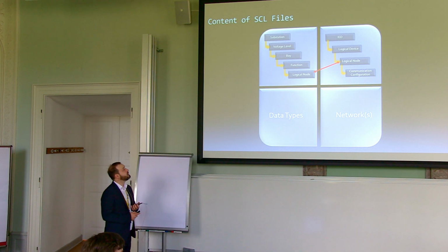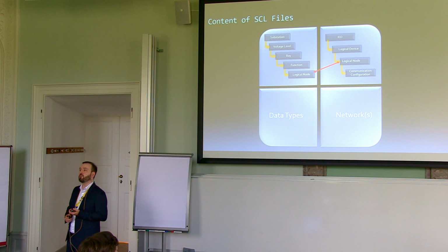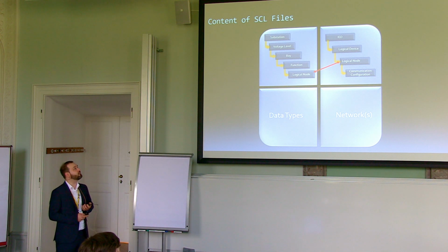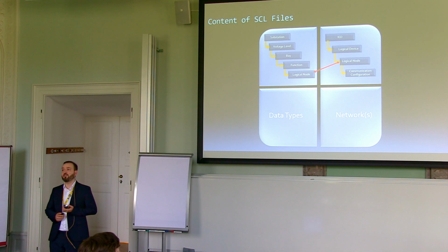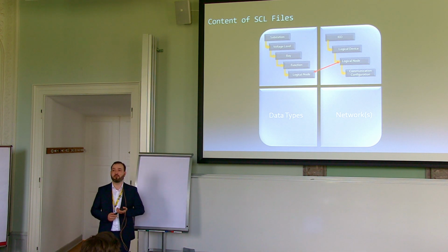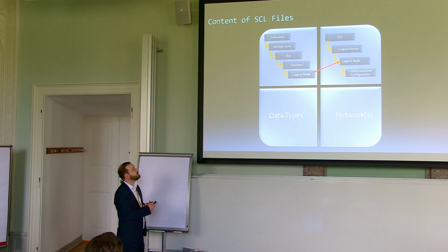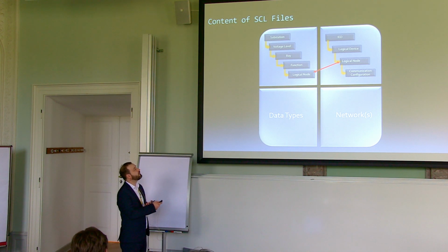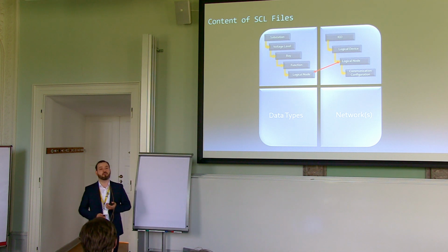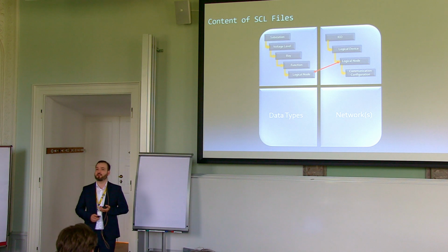So this link is not necessarily present at all times. When you start to design your substation, you may not have included the IEDs yet. You will have logical nodes of types that have nothing to do with any real device. But at some point, we will establish a link between these two sections. And hopefully, when you are done with the engineering process, all of these will have found their respective partners.